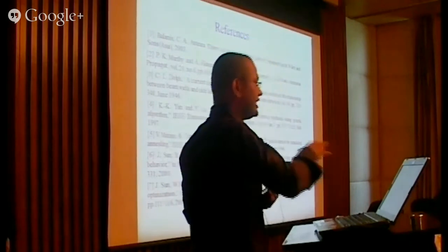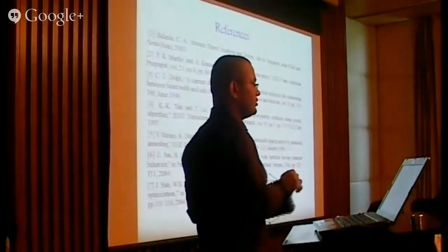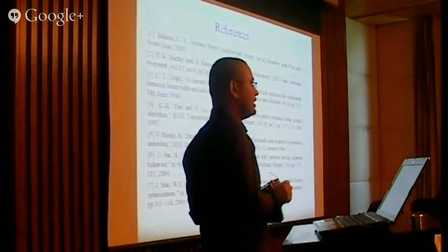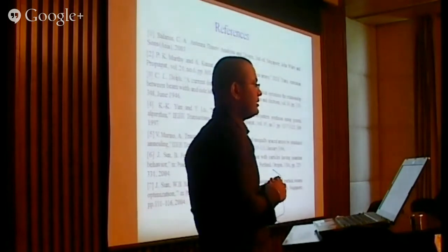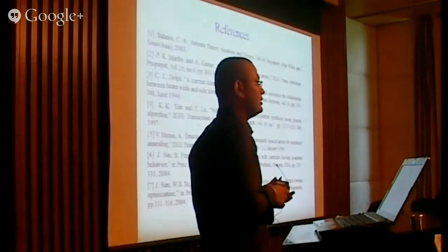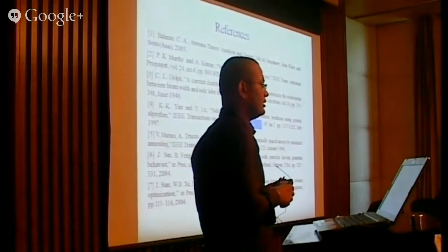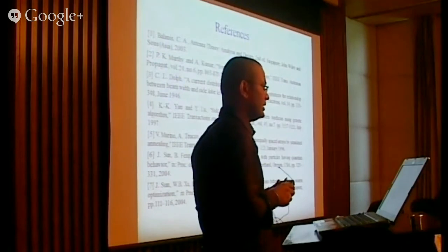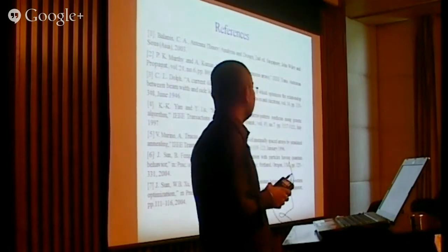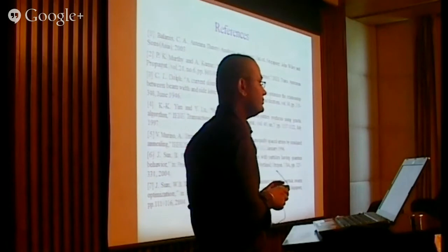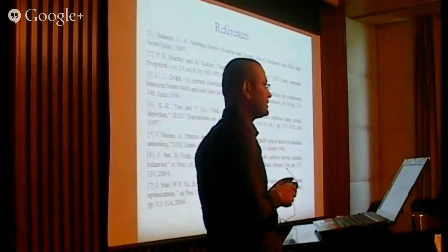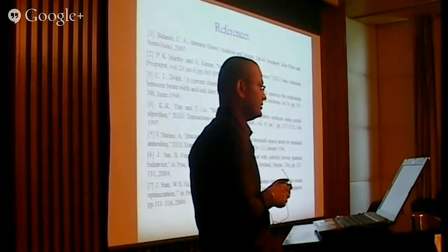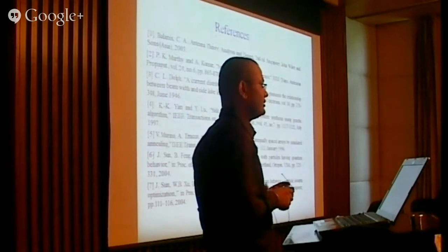If you want to reduce the side lobe level more, you need more elements. Again, people have reported it. The crux is that the sensitivity of the design increases as you go for a lower side lobe level with the same number of elements. So if there is a slight change in the current distribution, the side lobe level is going to change drastically.